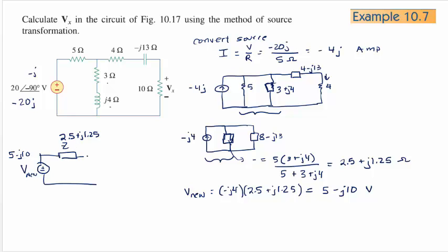So this was a block right here, an impedance block 4 minus J13, and then we have this resistor that we're interested in, which is just a, oh, I messed up, that was a 10, so that would have been a 14 right here. So okay, and that's 10 ohms. Okay, so let's just use voltage divider formula.